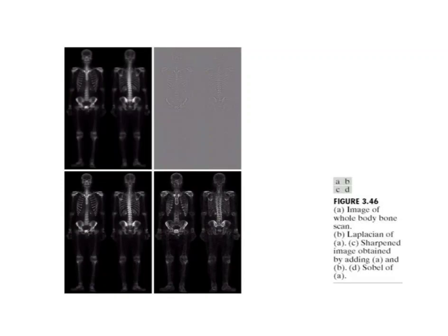One way that comes immediately to mind to reduce the noise is to use a median filter. However, median filtering is a nonlinear process capable of removing image features. This is unacceptable in medical image processing. An alternate approach is to use a mask formed from a smooth version of the gradient of the original image. The motivation behind this is straightforward and is based on the properties of first and second order derivatives.